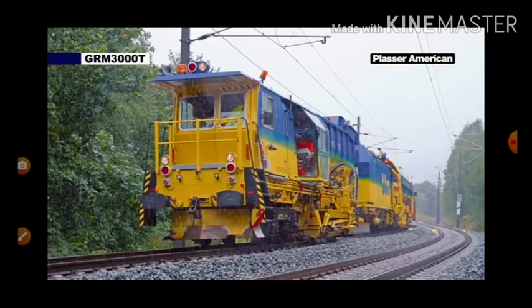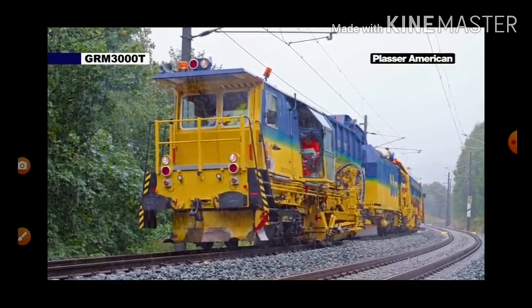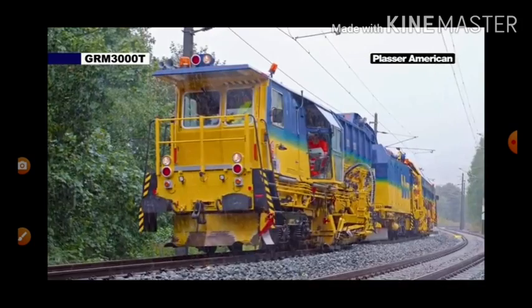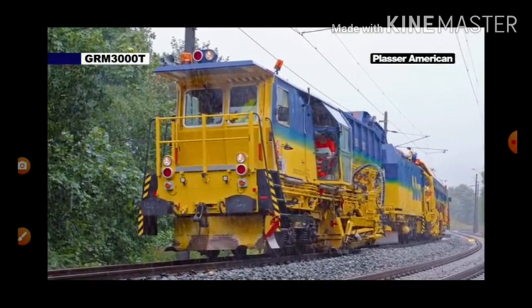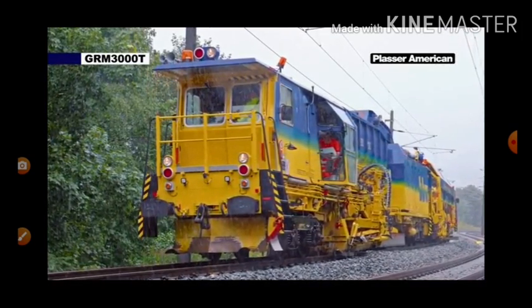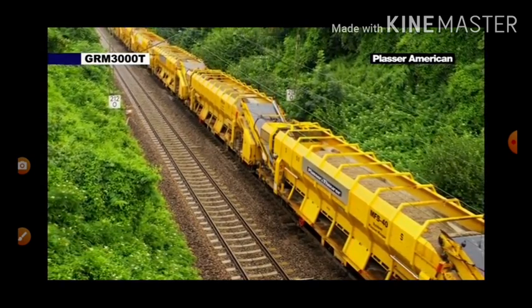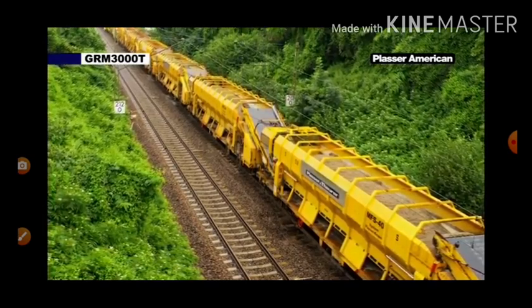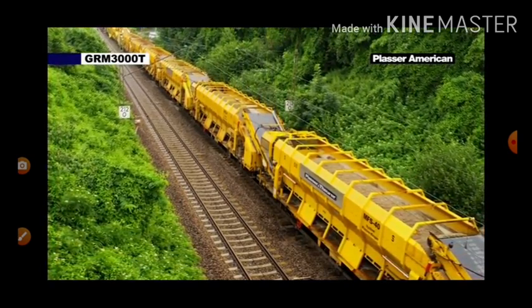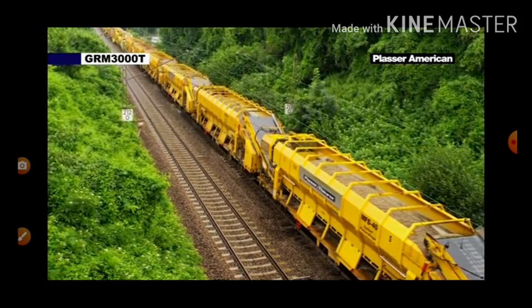Of course, there will usually be trains of different types, with permitted speeds at different levels, which travel the same curve. Also, there will be occasions when trains stop on the curve. This means that the degree of cant has to be fixed at a compromise figure to allow the safety of stopped trains and the best speeds for all the trains using the curve.